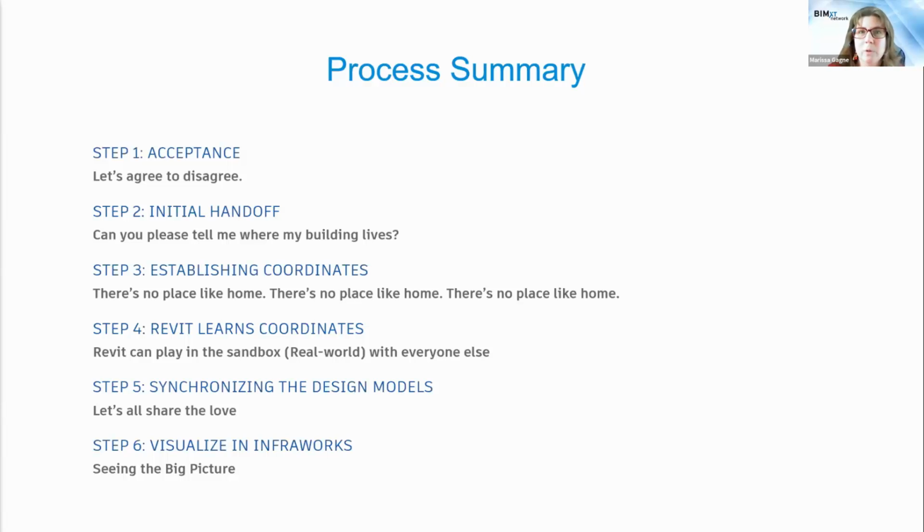And so that is absolutely important. The surveyors are the ones that are going to establish where the existing part is and where the site is in the world. And then we are the ones that have to decide where the building is going to go on the site. So basically Nick will hand me a floor plan, or a floor outline, and I stick it into my site and rotate it and put it in the right place. And then I'll have to send him coordinates. He's going to tell me what his origin was, and I send him the coordinates and the elevation of where I think that should be.